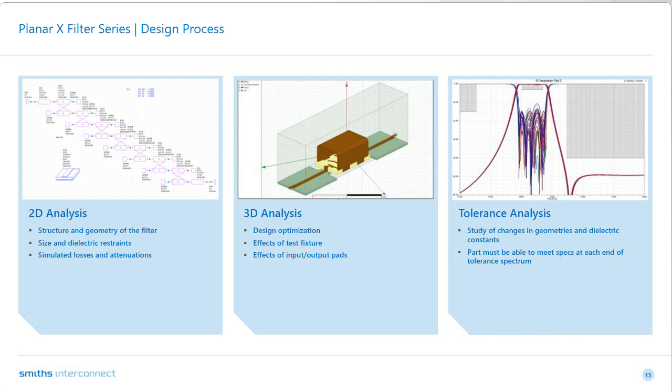These resonator geometries produce a much more selective high side of the filter. This is due to the parasitic coupling introduced when resonator structures are placed in line and close in proximity. This type of filter does shrink the size, but needs a plated via for each resonant structure.